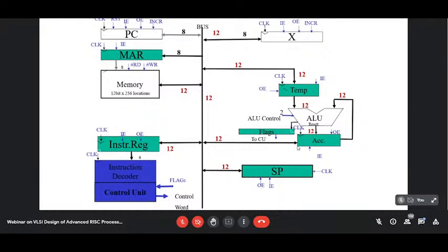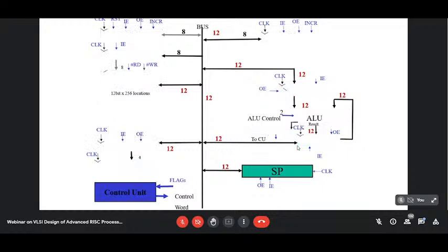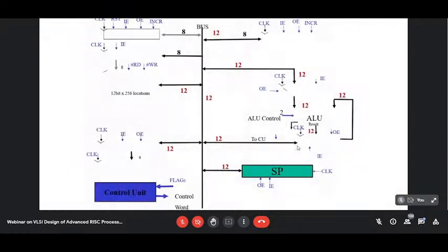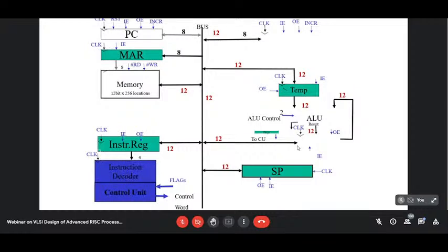So to design this CPU, from the instruction set architecture, you can easily make this schematic. So what do you require? First, put the special purpose registers like the program counter and instruction register over here. Memory is outside the CPU, mind that. Now for the program counter, there must be a bus. So the rule of making the architecture is to draw the bus. So what is this bus size? 12 bits, which includes the total instruction.